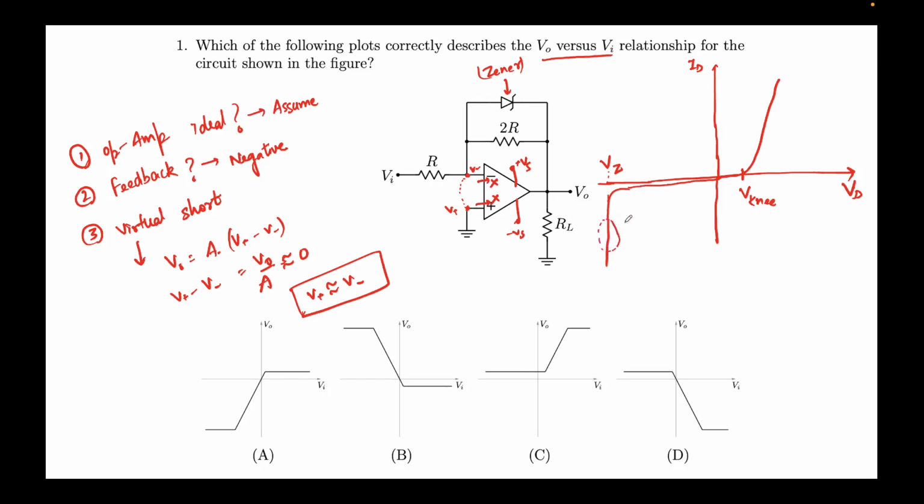Note that the current will be very high. The current here is a few nanoamps, a very small leakage current. The current here will be a few milliamps. So this diode can even be used here, and the current also here is usually a few milliamps after V_knee in the positive, positive bias side. This is forward bias in the first quadrant, reverse bias in the third quadrant. So you can use the Zener diode in this mode also, and the beauty of it is that the voltage will remain fixed. This means it behaves as if it were a voltage regulator. The voltage cannot increase further, but the current can be increased, obviously up to the limit that we do not burn the Zener diode.